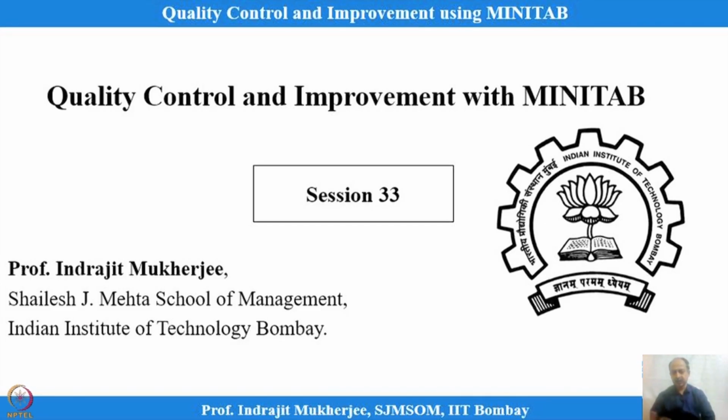So we are discussing measurement system analysis, and within that we are discussing the gauge R&R study, repeatability and reproducibility. We are taking some examples to understand, and we have seen that percentage contribution is one of the measures that needs to be considered, and study variability can also be considered. How much is the instrument variation with respect to study variability, that also we have seen how to interpret. Let me just go back to that and the analysis part of that.